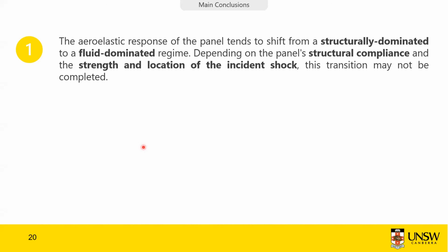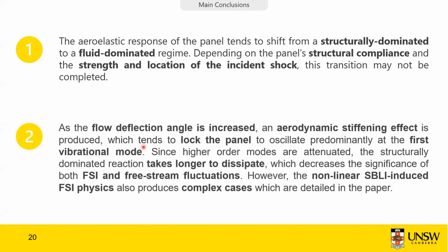The second major takeaway of this study is that as we increase the flow deflection angle of the shock generator, we produce an aerodynamic stiffening effect, and that tends to lock the panel to oscillate predominantly at its first vibrational mode.